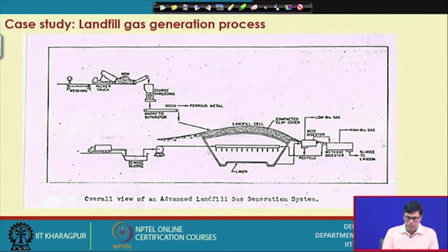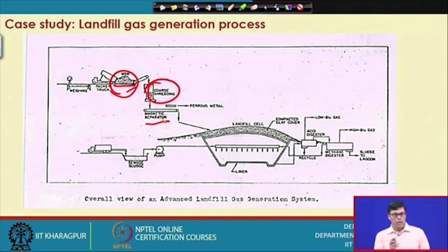This is the dumping area of this process, and here the truck comes onto the weighing machine. We take the weight and it is unloaded here, and then the truck goes there again. The difference will give you how much waste material they have unloaded, and then you use the shredding machine. Shredding machine means it's degraded into small pieces, and then this is the magnetic separator, where we can separate the iron-type material. We get the ferrous material out, and then we put the rest in the landfill.